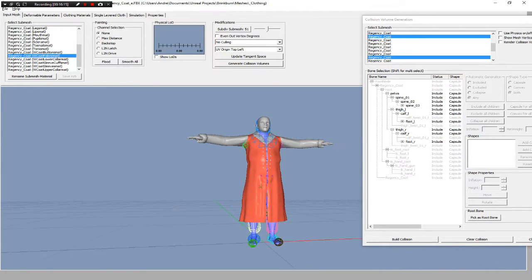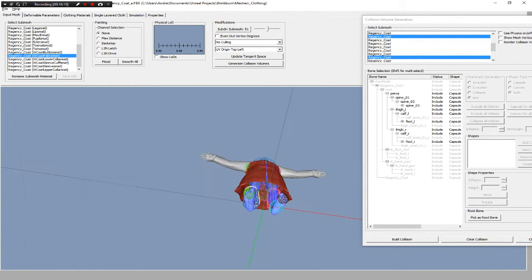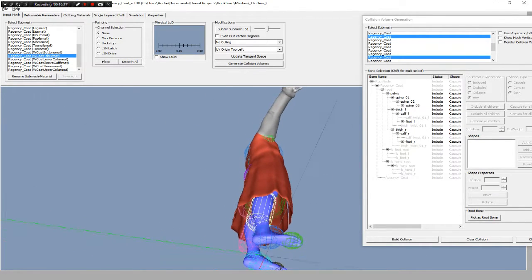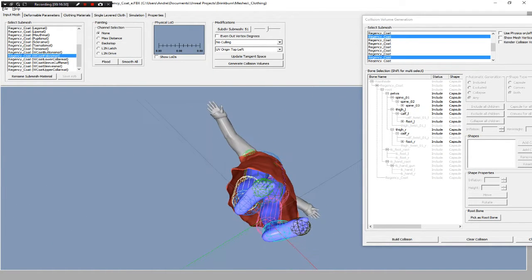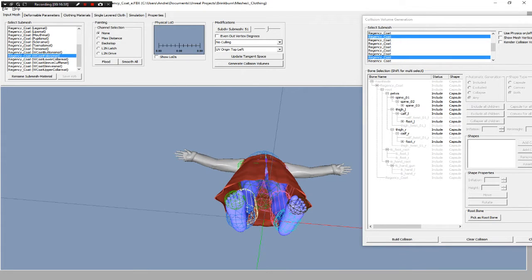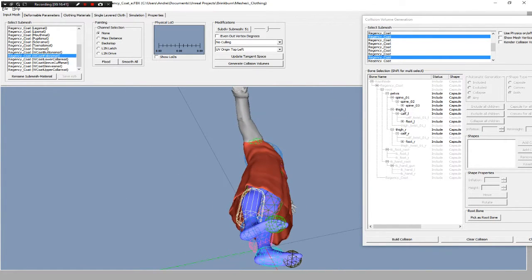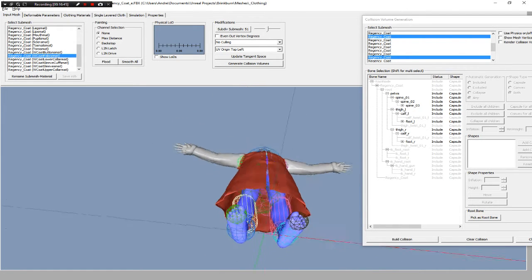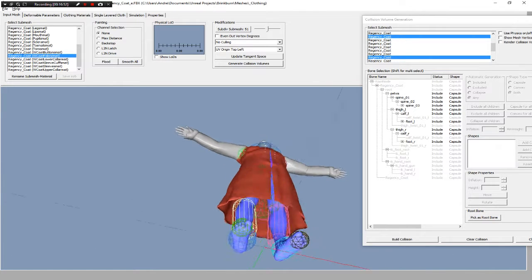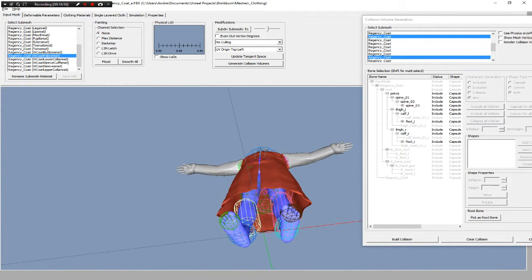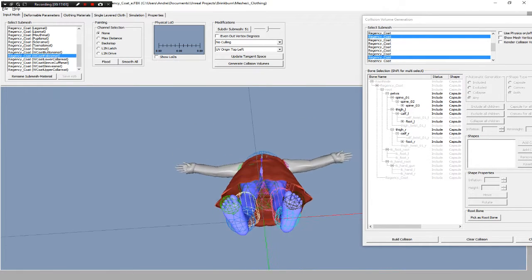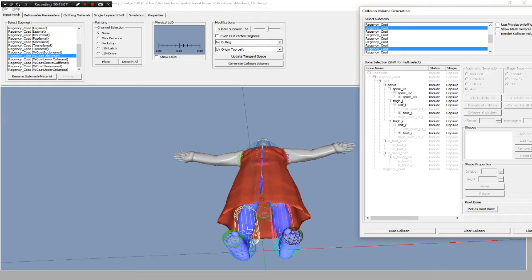The second thing is, I'm sure, as I've seen in other tutorials, that Maya and 3D Max do this better than the standalone. As you can see here, this has generated collision, but this has capsules around areas of the body. Whilst in Maya and 3D Max, you might find that it detects the edges of this mesh, and it allows for better collision. Now the thing is, if you don't have a mesh in those plugins, it won't do the detection really well. Whereas in this NVIDIA SDK, it doesn't matter because this mesh isn't really used for edge detection. It's just a skeleton.